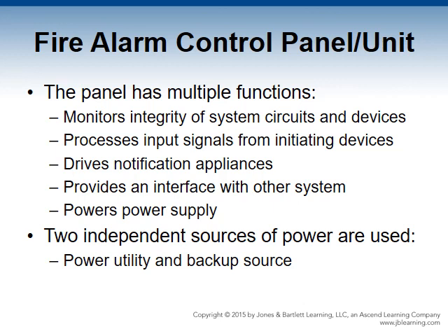How do these systems work? These panels have multiple functions. They monitor the integrity of the system circuits and devices, and process manual and automatic input signals from initiating devices. They provide an interface to control or activate other fire protection and building systems. They provide power supply to support all systems and devices.